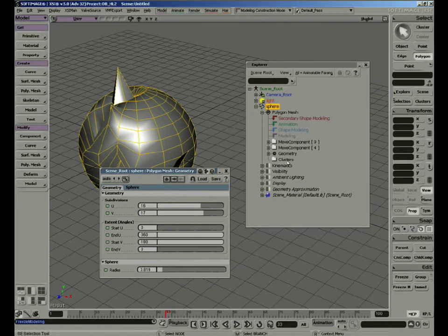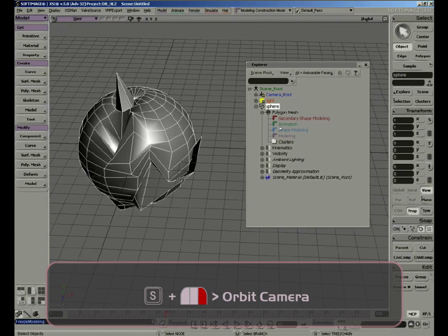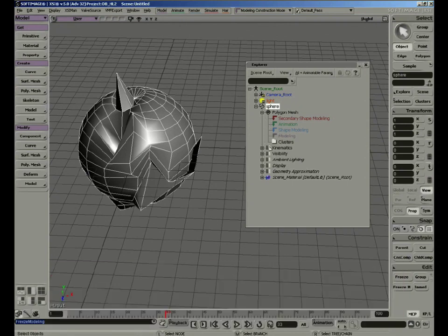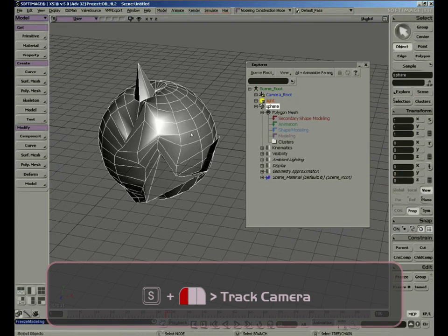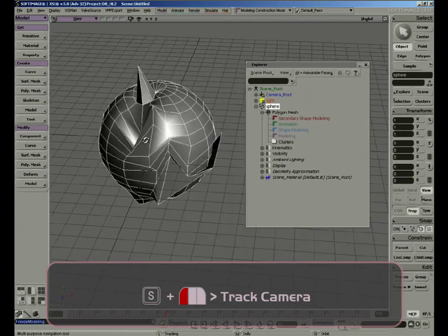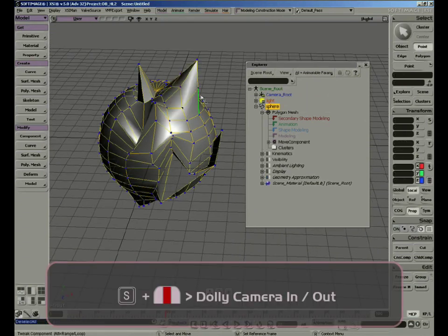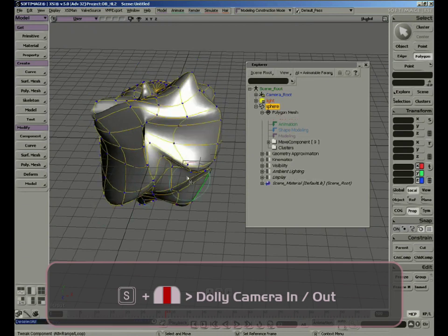So select the object and click Freeze M. And all the operators are gone, but the model is still modified. As you can see, I cannot return to the model's geometry page. Even if I hit Enter, the property page will only have its name and its subdivision type. And if I keep modifying the object, the stack will continue to grow. So we can see more operators being added.